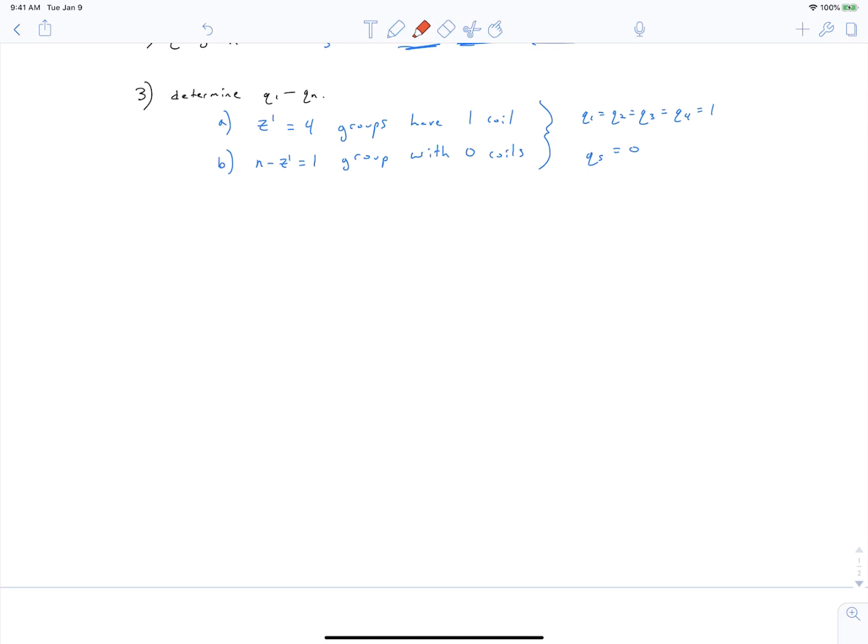However, you can see from this it doesn't really make any difference whether you put this 0 slot phase zone in the middle up here or if it's on the end. This sequence is going to repeat itself, and so because there's only one slot that's different, or there's only one coil group that's different, it doesn't matter where you place it.